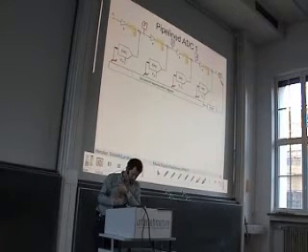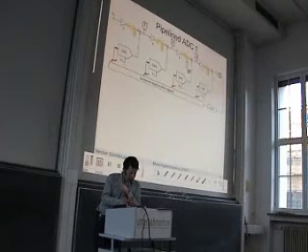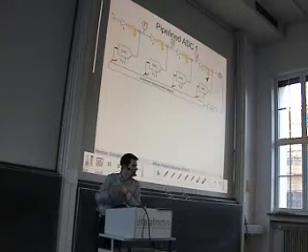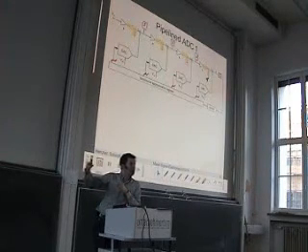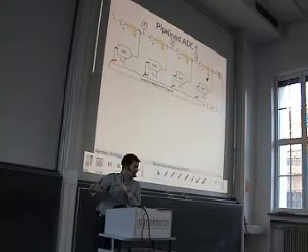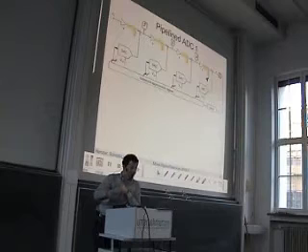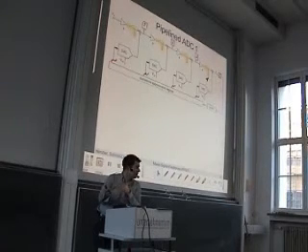So still it means that it takes n cycle times to pass the data through the complete pipeline. So the conversion time is not accelerated. But what is accelerated is that after each cycle, new results come out of the ADC.